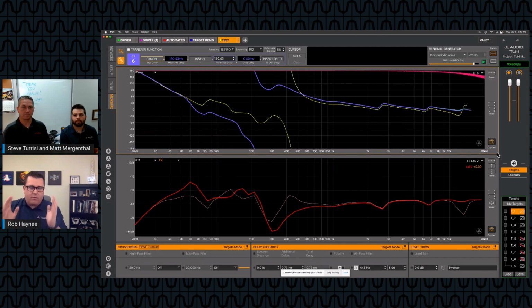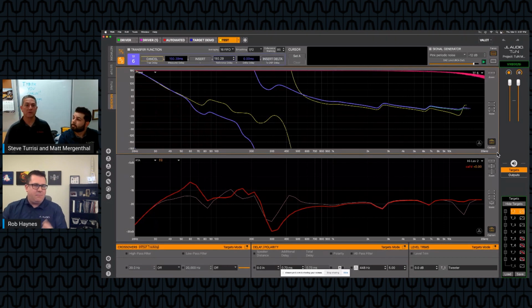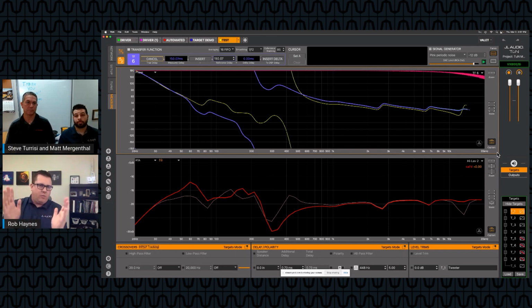If you had super expensive test equipment, like our engineers have maybe, but even there, it was a challenge. But for a retailer in the shop trying to figure out how to properly integrate or tune a car, this is without a doubt the easiest and most visible way to precisely know where not just the all-pass filter is set, but we can start to see the width of it and get cues to make adjustments. It's all in front of us now.